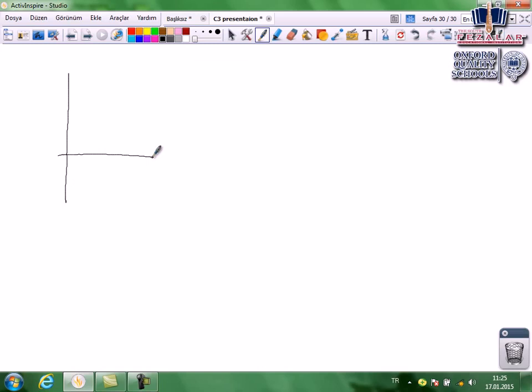For example, for parallel combination, if IC is greater than IL, here we have IR, and here we have voltage. If IC is greater, that means IX is drawn in that direction, and for IX and IR, the total current is drawn in that direction. As you see, current leads voltage by phi. At this time, the circuit is capacitive. Remember, AC circuit with pure capacitor.